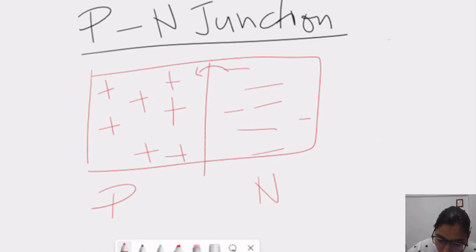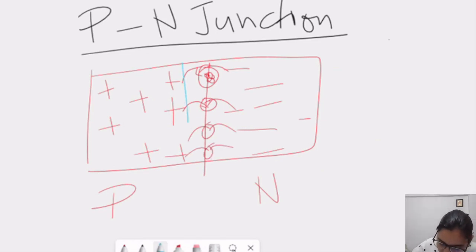And these holes try to penetrate the junction and come to this place, but in between they diffuse with electrons. So, the electron and hole recombine here and become neutral, forming a charge-neutral region. Again positive, negative, neutral charge. So, what is happening due to this process? A layer is formed here.